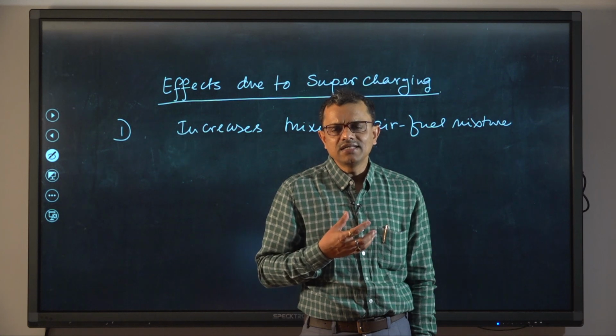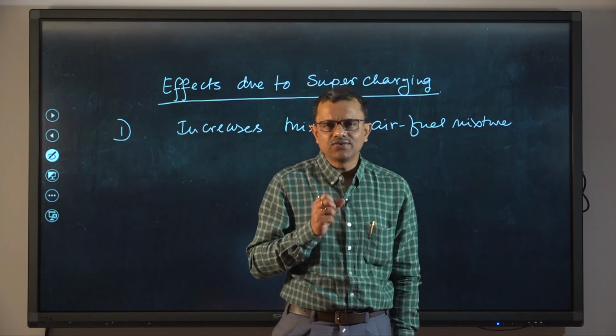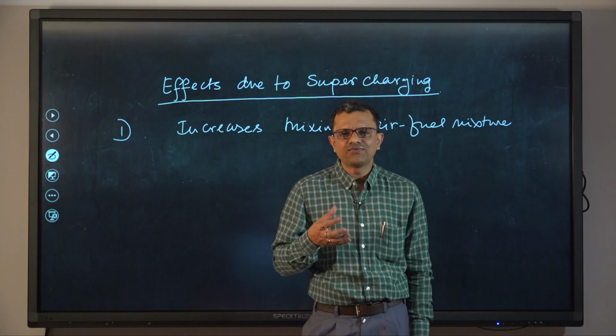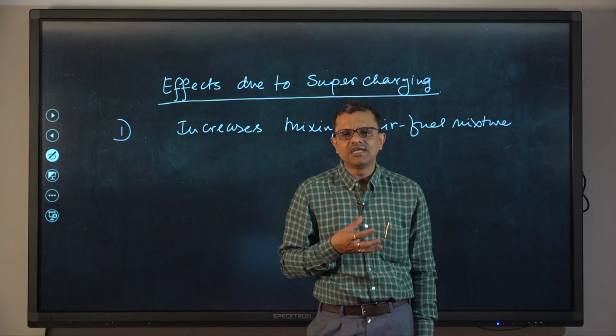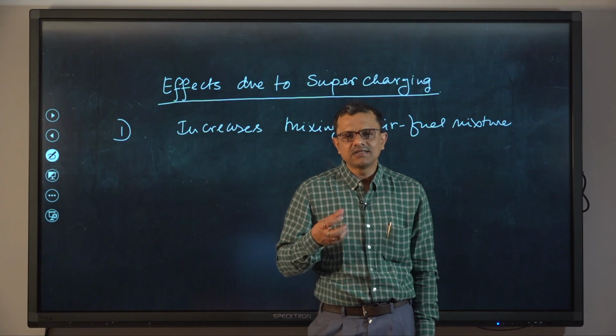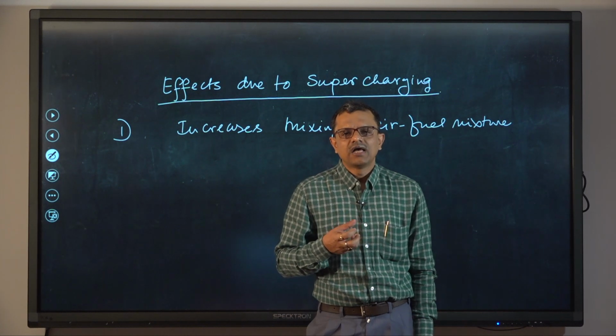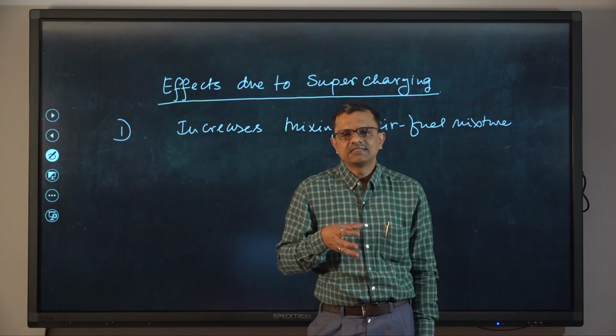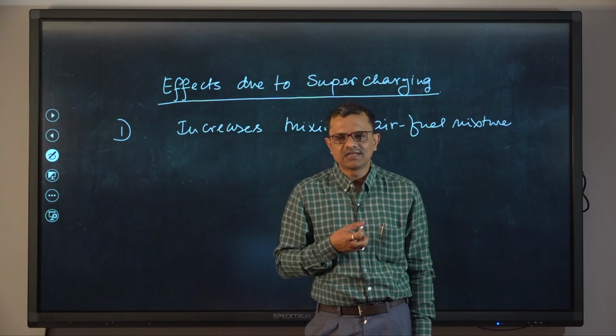For SI engines, or even, as I told you many times, for modern CI engines, since fuel is injected through a multi-port fuel injection system, sometimes even in the intake manifold, the injected fuel is allowed to mix with the incoming air stream.